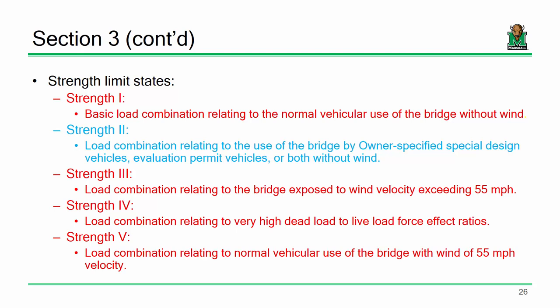In building design, I don't know that it's as specifically laid out like this, like it is in the world of bridges. You've probably seen 1.4 times the dead, 1.2 times the dead plus 1.6 times the live, and you see all these load combos. Up until now, you probably thought, let's just put the loads in there, and the biggest number that we get, that's the one that we use for design. And yeah, there's some truth to that, but usually each of those load combos has a specific purpose, okay?